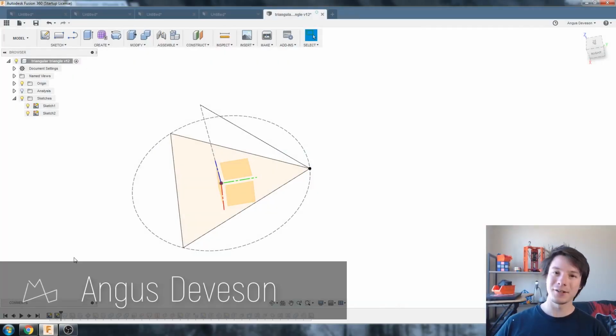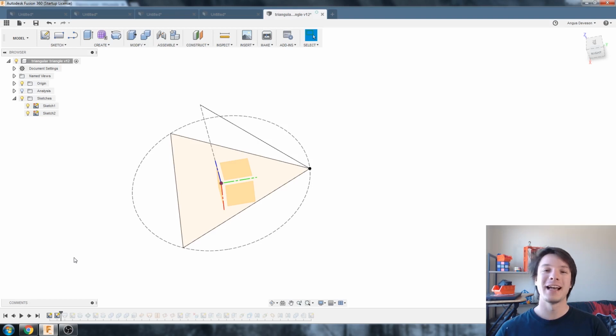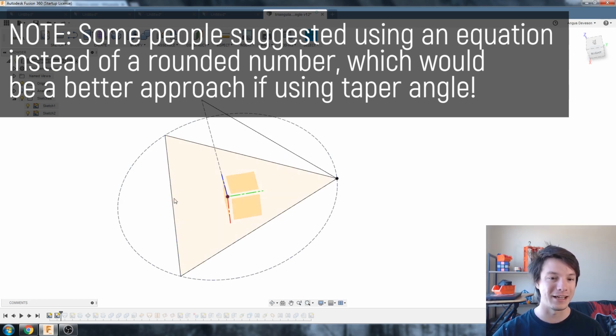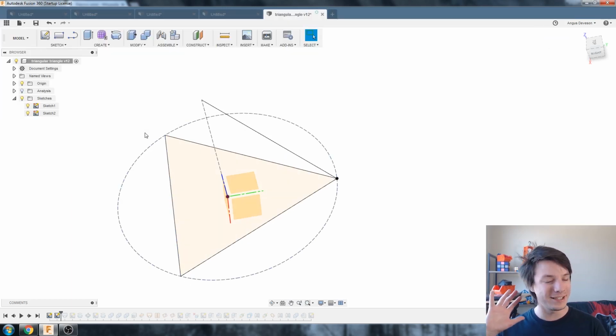Okay, so the basis of our Reuleaux tetrahedron is actually a regular tetrahedron, and in the previous video I showed you how to draw that properly, in my opinion anyway. I'm not using an extrude with a taper angle because that uses rounding. I'm actually going to draw it again like I showed using a loft, but you don't strictly need it to create the Reuleaux tetrahedron because we're going to be using spheres that intersect with each other. It's more of a scaffold.